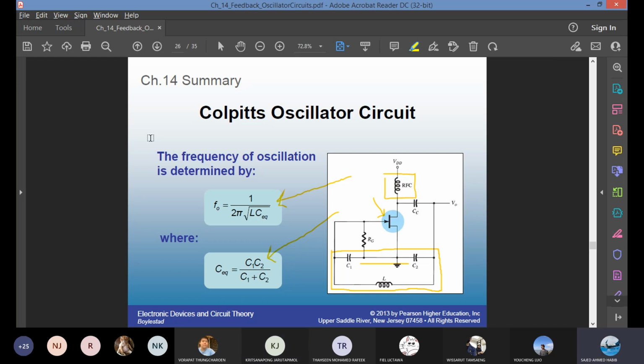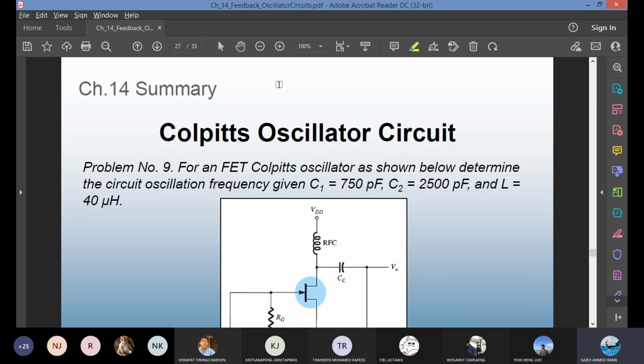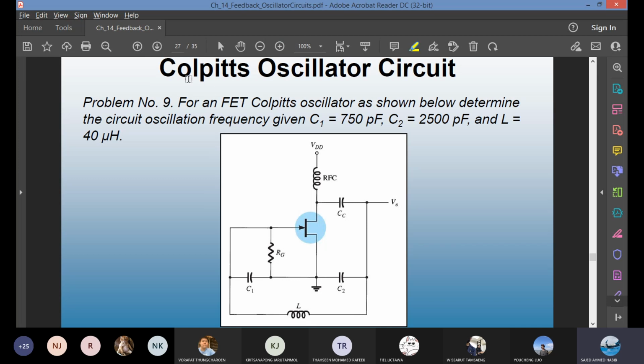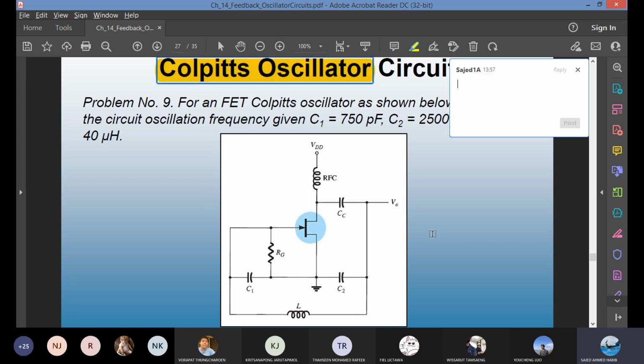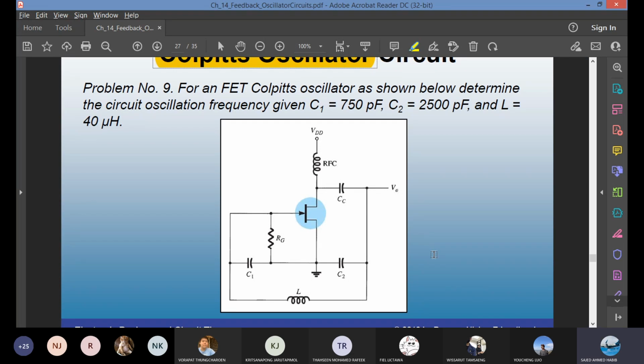I don't have any. So right now, let's try to solve very straightforward tuned oscillator problems. Given a Colpitts oscillator circuit, sometimes in the exam, it says, given the tuned circuit. It doesn't say Colpitts or Hartley. You have to figure it out. The trick to figure it out is to look at the tank area, called the tank circuit. If you have more capacitors than inductors, definitely Colpitts. And remember the shortcut: Colpitts, the first letter is C, and more capacitors, the first letter is C.